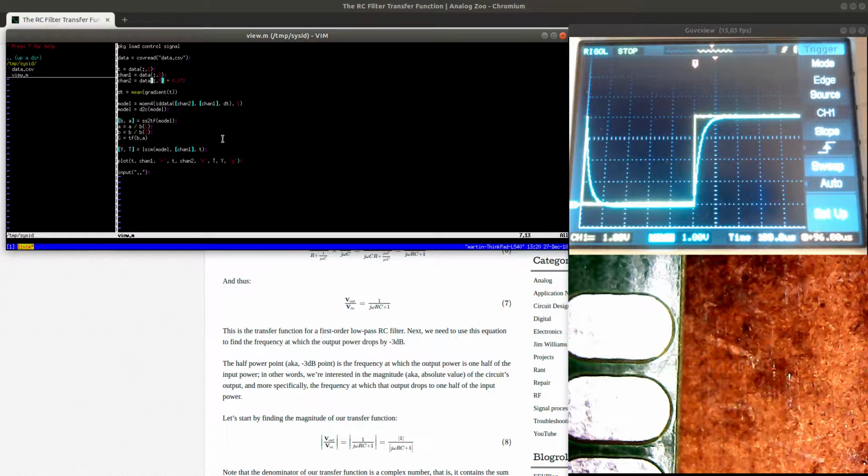Let's actually resample this data. Let's use a fixed DT so that we don't need to do this ugly approximation. We just set DT to 0.0. Let's say in this case it will probably be reasonable to use 1 microsecond because it's a rather fast response model. So 1e-6.